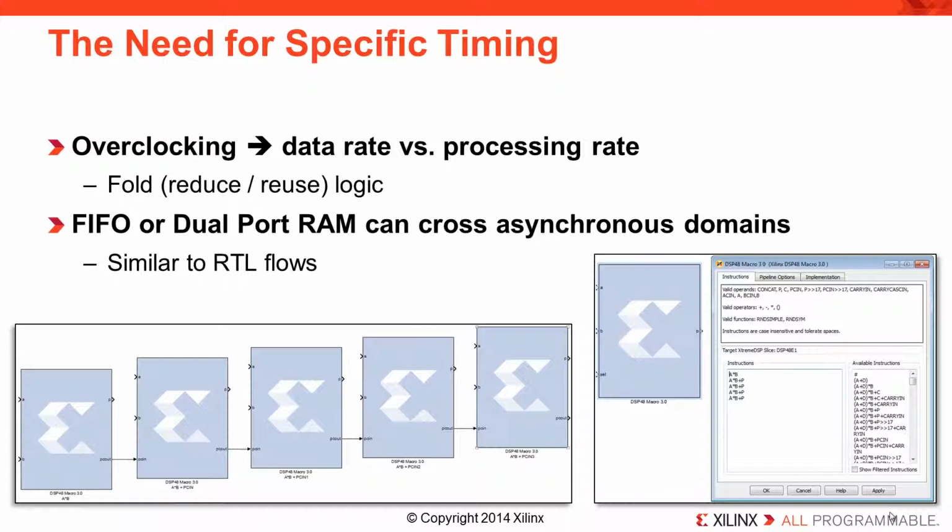A common way to get the most out of the DSP hardware design is to overclock the resources. This allows the sharing of a multiplier across numerous taps of the FIR filter. So instead of using 40 DSP slices running at 100 MHz, we use 8 DSP slices running at 500 MHz. Parallelism and folding techniques can be combined to take advantage of the FPGA's programmable logic. Since we're taking advantage of the direct connectivity between the slices, we also get the lower power advantage.